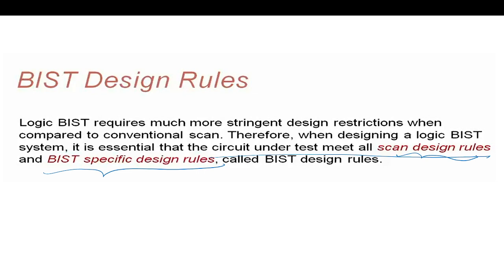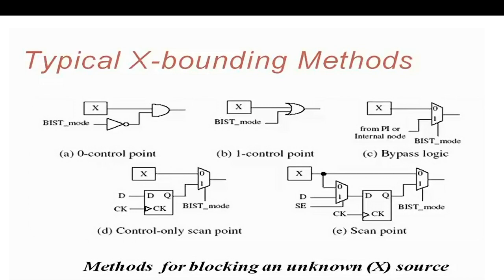We have seen the scan rules already in the initial classes. Now we will see the rules specific to BIST. If we have a don't-care value propagating to the output, we will not be able to know whether the output is because of the fault or because of the don't-care.